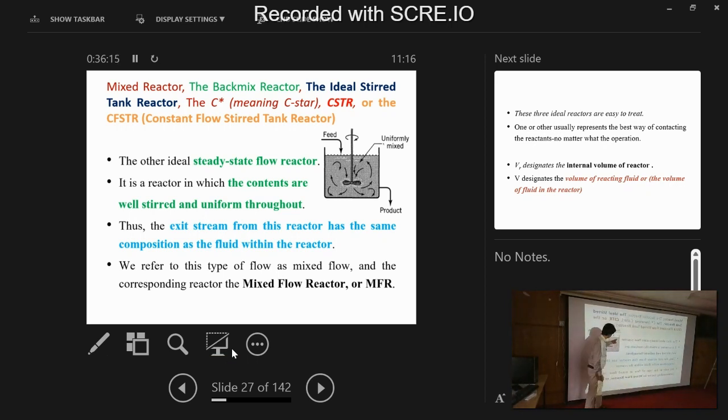Look at the reactor here. This is a type of CSTR where I am feeding the feed in and out. If I feed the liquid or the reactant here, I am giving the stirring option. That means mixing is there, a well mixed case. But some fluid particles may be left here, or come over here, or the same fluid may be going back up. See the directions. Or sometimes, when I feed here, some of the liquid particles directly go back and come out, called overtaking.